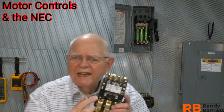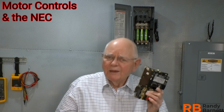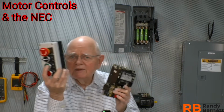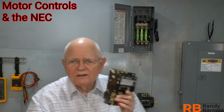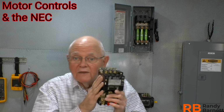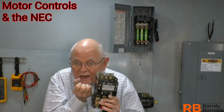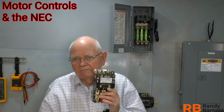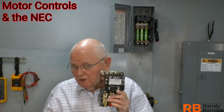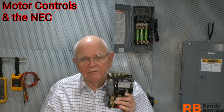Well, if I don't want to stand here and manually operate these contacts to start the motor, I'm going to do it remotely. As I mentioned, I'm going to take something like a push button, push my push button, and energize a coil of wire. And when I energize that coil of wire, the electromagnetic field around that coil will pull this little lever on the inside and close those contacts. And so I need to energize and maintain that coil energized as long as I want to keep the motor running. I need to keep the contacts closed, obviously.